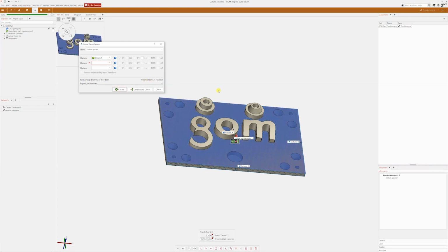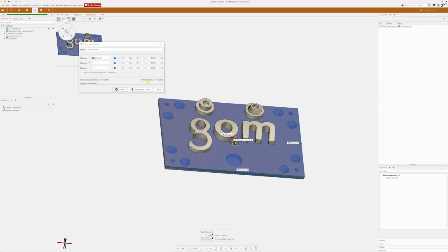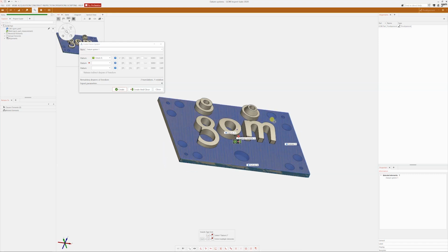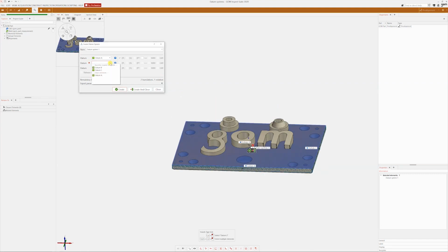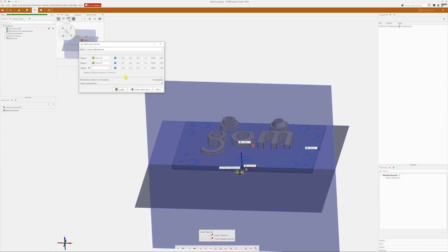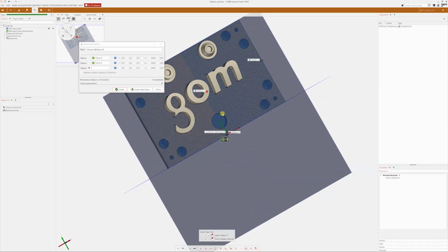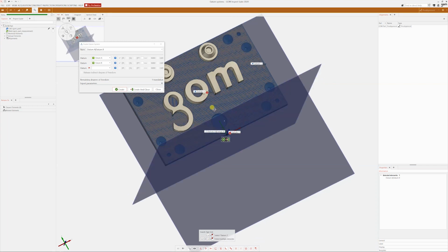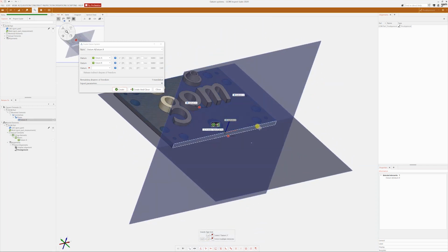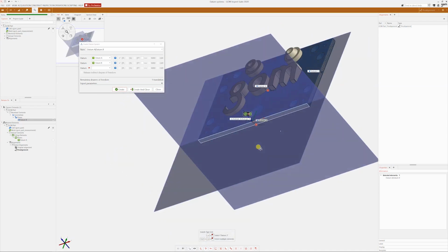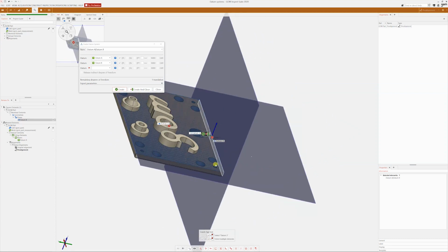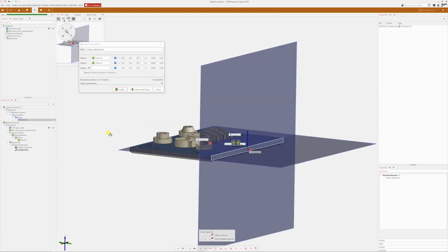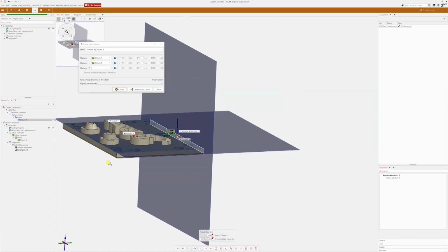and as we see here, it remains 2 translations and 1 rotation. So datum A took 2 rotations and 1 translation. Okay, good. Datum B will take the other rotation and 1 translation, so it will take the translation from here and the rotation from here, so the part will not move like this anymore. Datum A took the rotation from here, so the part will not rotate like this.